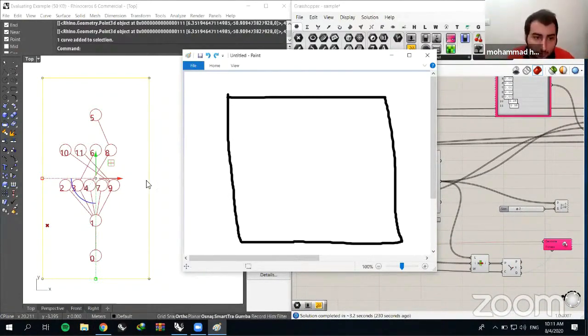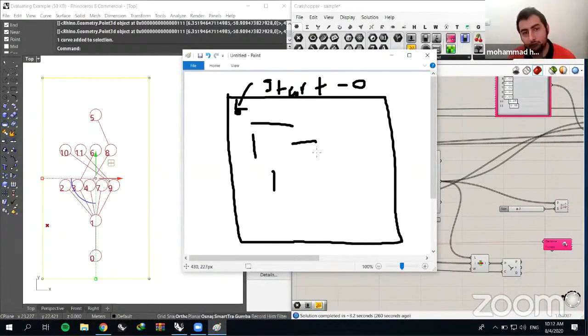the boundary. So, for example, I put in this imaginary thing that we just drew here. I'm trying to set space 0 here. I set a start point and define its index as index 0, which is how the spatial graph understands that space 0 should be located in the place where I set the start point. Then it starts the separation of the spaces